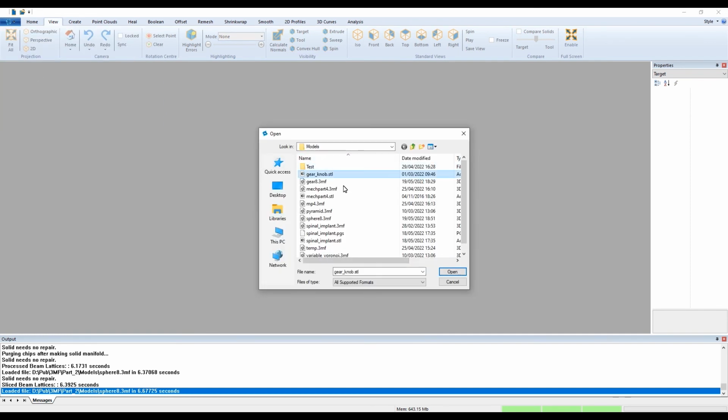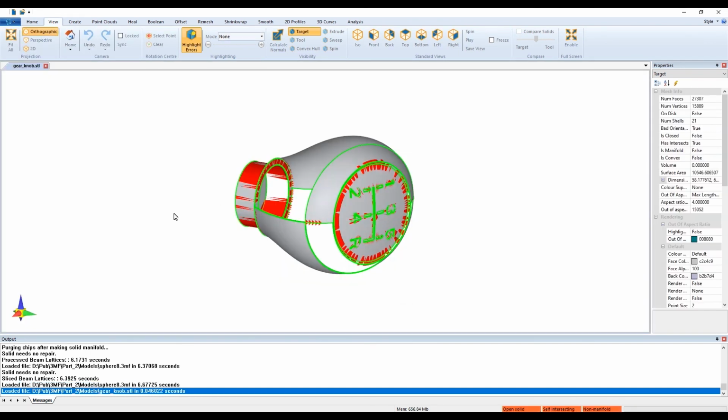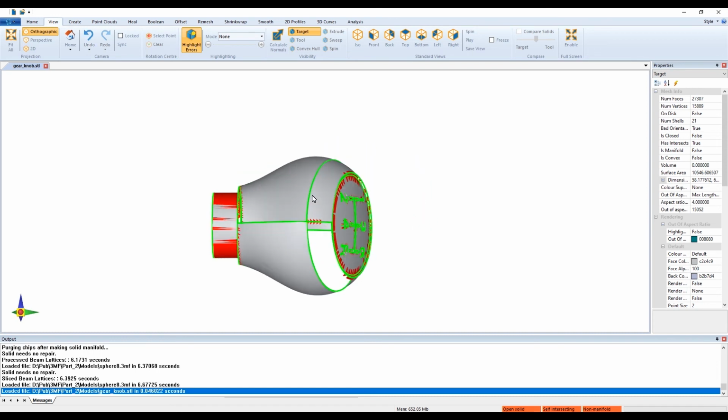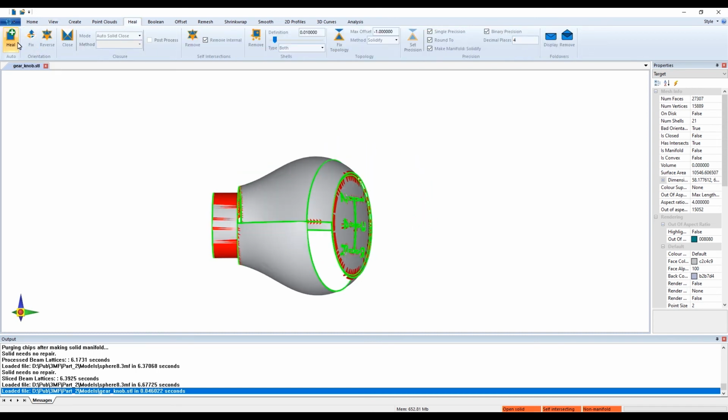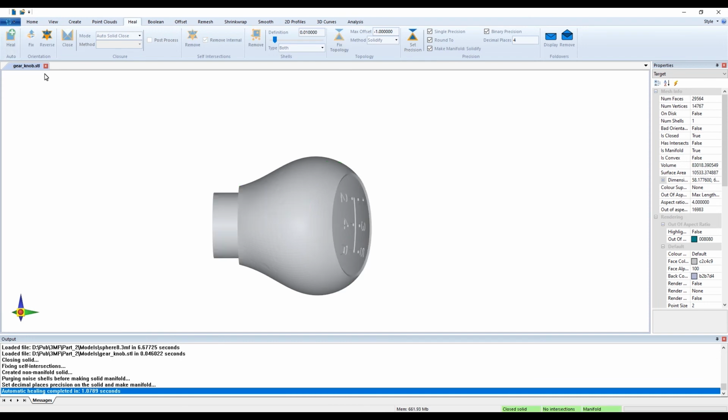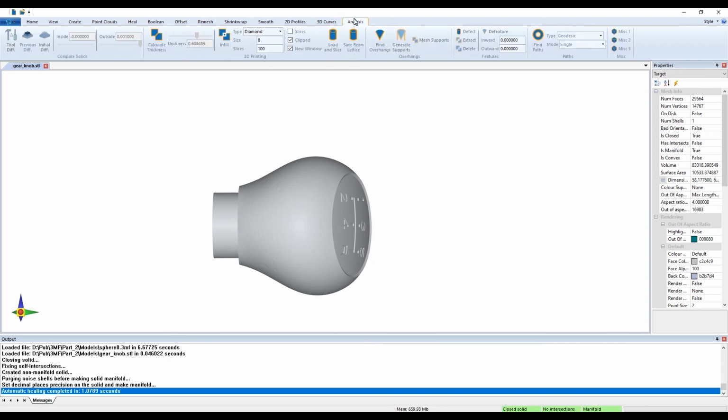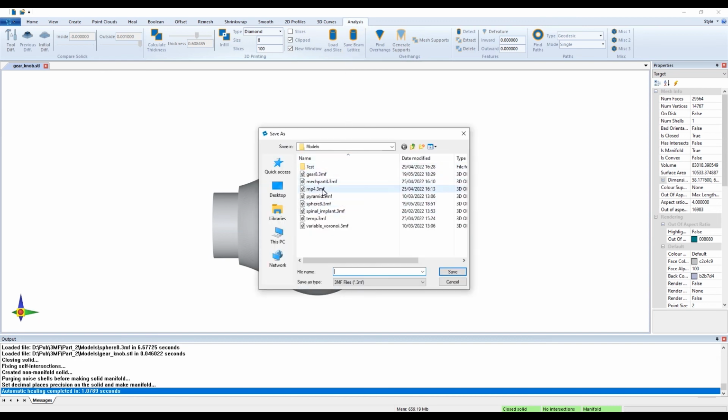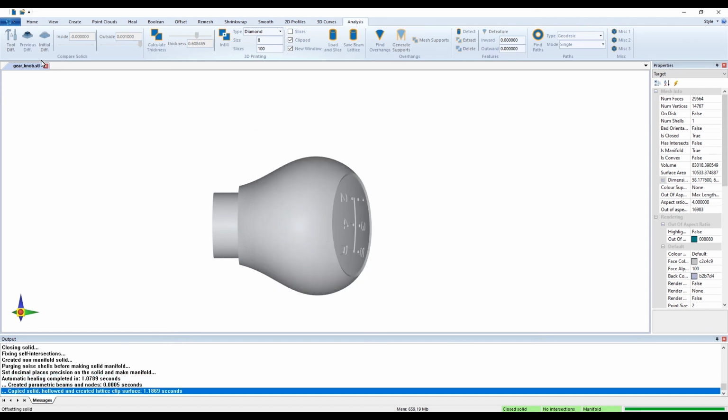We're going to load in this gear knob STL. We can see that it's typical of some surface models. The orientation is inconsistent and there are gaps between the different surface patches. So we're just going to give this a quick auto heal using Polygonica. And now that everything's good, let's export it to 3MF with a lattice. Same again, using the 8x8 diamond lattice. We'll overwrite the example one that I've done. And then we'll load it back in.